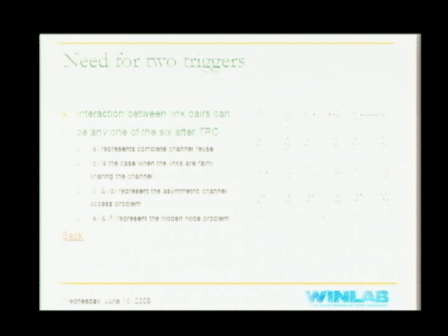So for the channel reuse, it's more like a cellular network. The fact is it's the relative distances that, when they both transmit, give the dominant transmitter who's closer to the receiver a much stronger signal. The SINR will be roughly the same whether the transmit power is high or low. Changing the transmit power doesn't change it. So basically the SNR is unchanged.